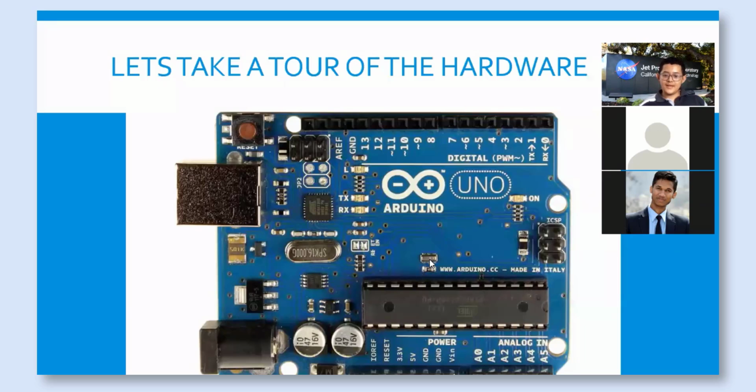It has a 16 megahertz oscillator over here, which sets the clock speed of the controller. To program this controller, there is another microcontroller over here, which is an ISP programmer. This also has a 16 megahertz oscillator, and it converts the USB data to ISP and then programs